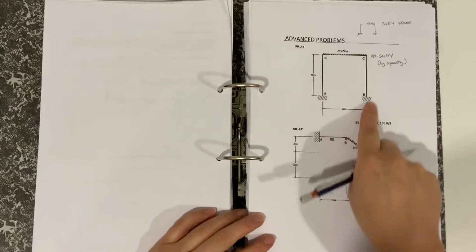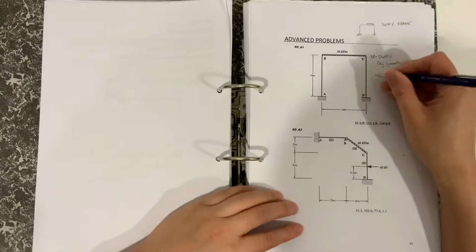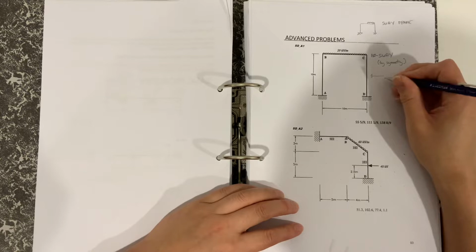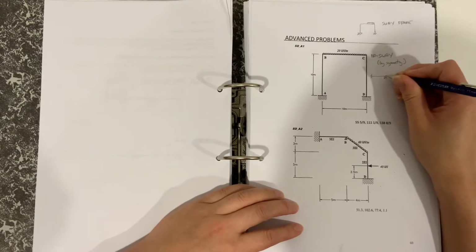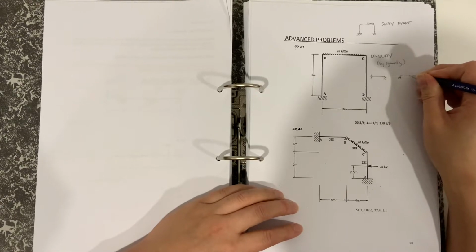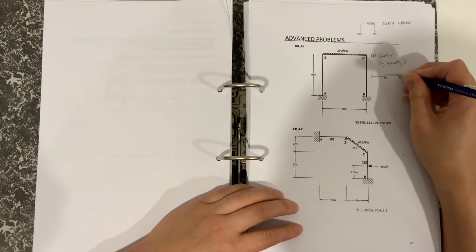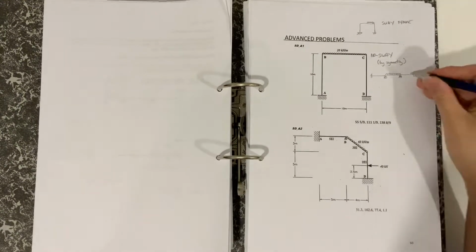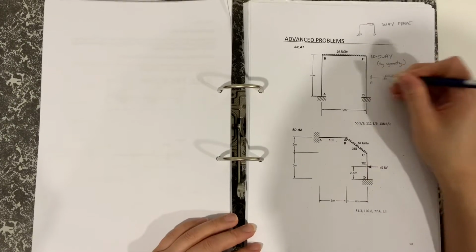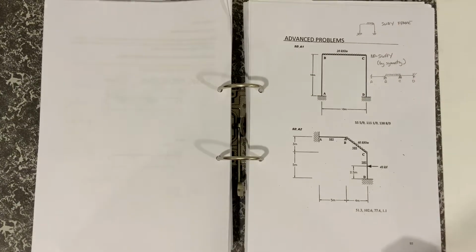So we've got a frame. This frame can sway, as we said, but if the load is symmetrical, it could be like that, and we would be able to say that would be AB, put B on the roller, and then BC, and then CD. So we could imagine that you can solve this problem here, that being A, that being B, that being C, and then that being D.